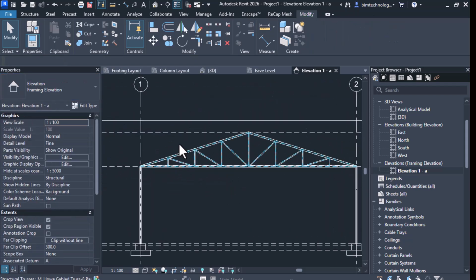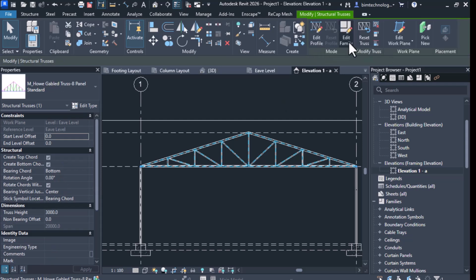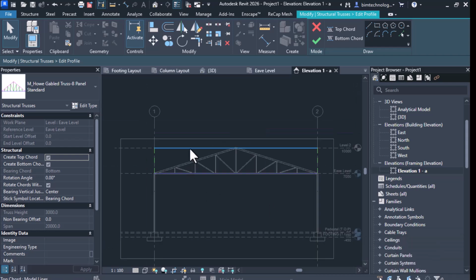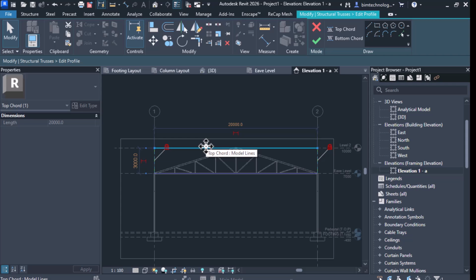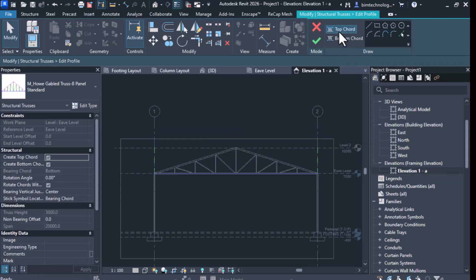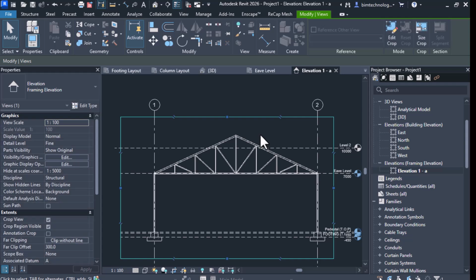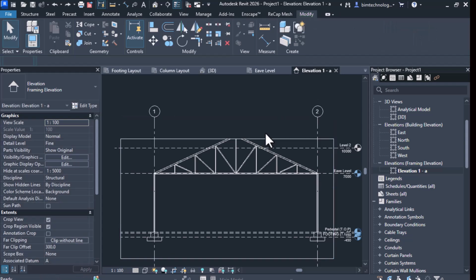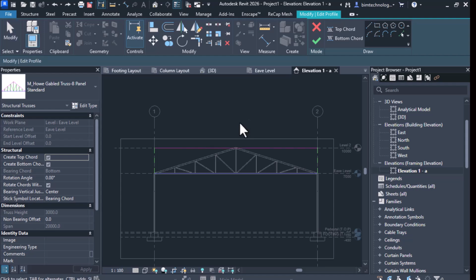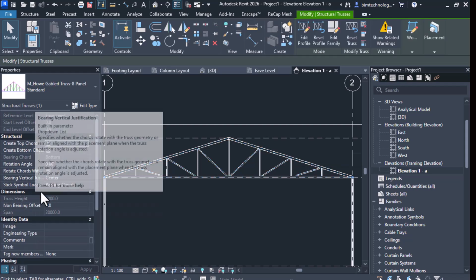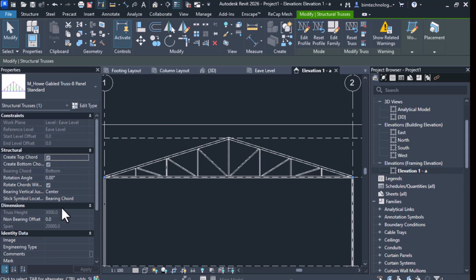And then if you want to change the profile, the moment we change the profile, you can have the profile set and delete it. You can change the shape of the profile, the top part. Let's say you want to have it in an arc section like this. So you can see the truss is changed accordingly, that particular arc section. There are various options in the trusses that you can basically go and start looking into in Revit.